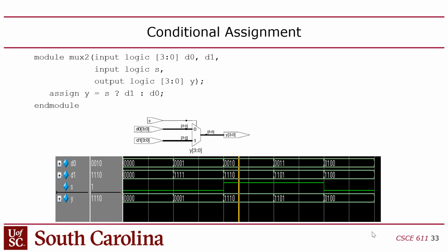But anyway, the point is that this is an expression you can use to create muxes. And in your CPU, muxes are fundamentally what's used to create data paths. This is how, for example, you can choose between writing the output of the ALU into the register file or writing the output you're loading from memory into the register file. That's a mux that controls that.